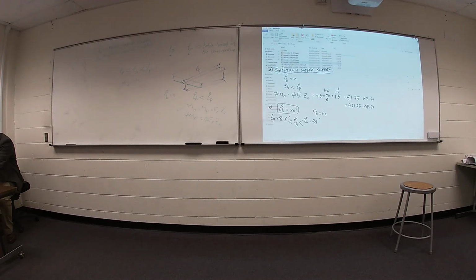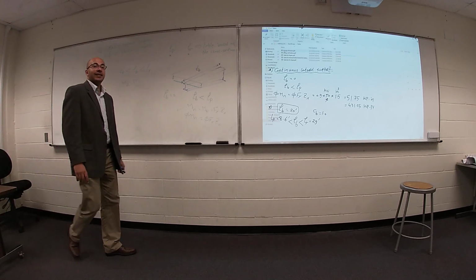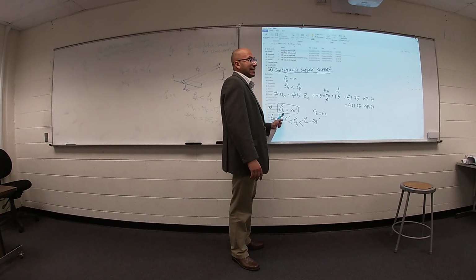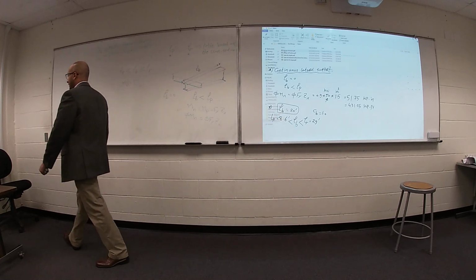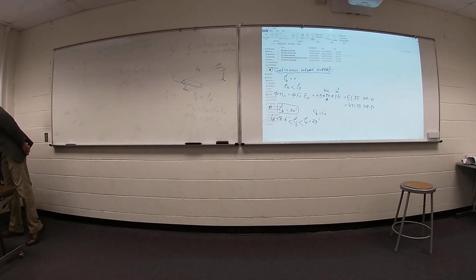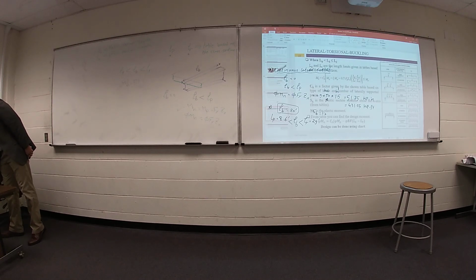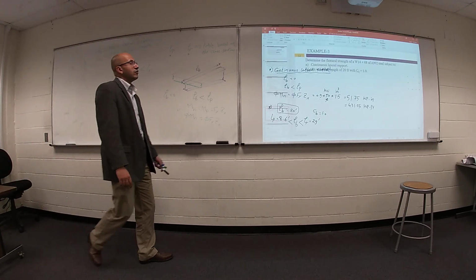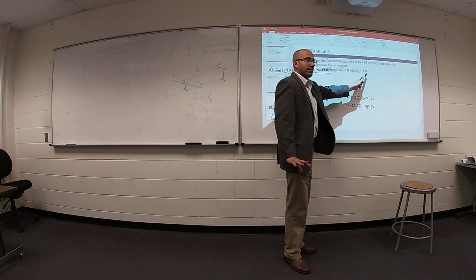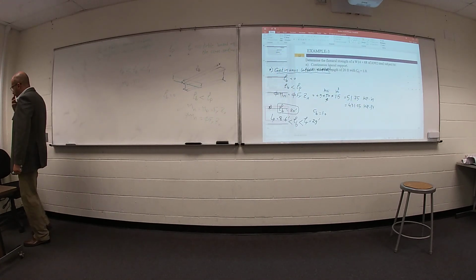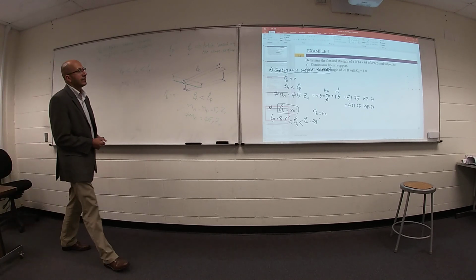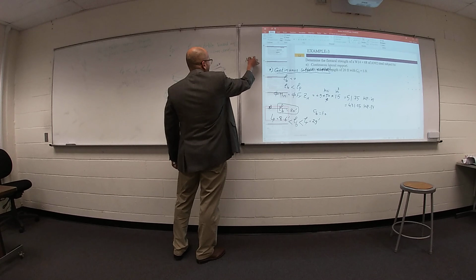Is it supposed to be CB or LB? In the example, LB is 20 feet, the unsupported length. CB is a factor given in the problem, and the table is just for CB equal to 1. Okay, I got it. That's all. So let's start. What is the name of your cross section? W14 times 68.